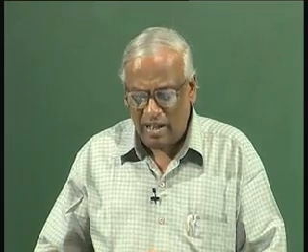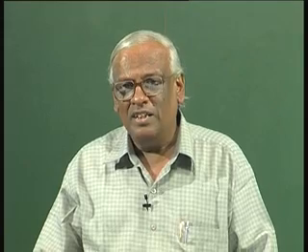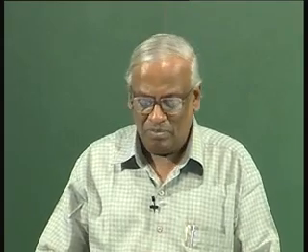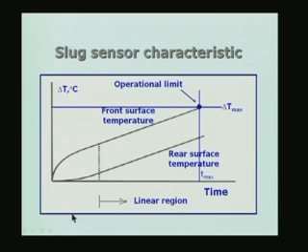But in practice, what will happen is, if the slug is not going to satisfy the requirement, then the front surface temperature and the back surface temperature will have a certain lag in time. So, I have just indicated what is going to be expected in actual practice. If you have a slug which is not thin in the sense we used earlier, the front surface and the rear surface temperatures are going to follow slightly different paths.